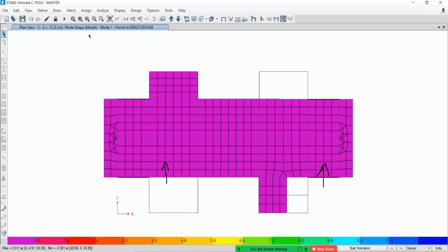But see, I am at the third level, and in that direction also it is stiff. High stiffness is there. Move to the next. Stiffness seems reduced as you move up the height of the structure. Actually, stiffness will be the same. The problem is that the intensity of the lateral force is going to increase. Am I right or wrong? Due to the increase of that lateral force, the stability of the structure is going to be lost.